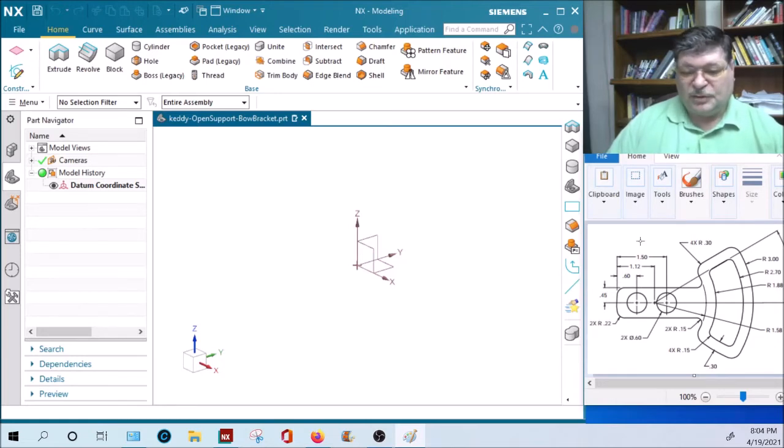per line. So with 16, take an average of about 3 constraints per line. 16 times 3 is 48, right? 48 constraints, 48 dimensions, if you will. That gets complicated. If we could dumb the sketch down, make the sketch simpler, then we're doing good. We lower the difficulty of the sketch.